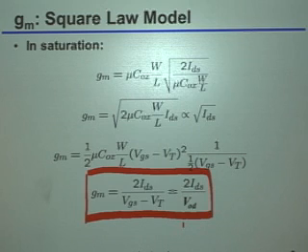That's certainly true. But on the other hand, you may not actually be able to reduce that overdrive arbitrarily, right? The particular effect that you mentioned was that, for example, I may enter the subthreshold region. We'll come back to that in 1 second. You also mentioned that if my overdrive is too small and my signal is really big, that may cause some nonlinear effects. That's also true, although we won't spend as much time on that this time around. We'll talk more about that a little bit later on. But there's maybe even two important things that also come into this trade-off in terms of how you would choose that overdrive.